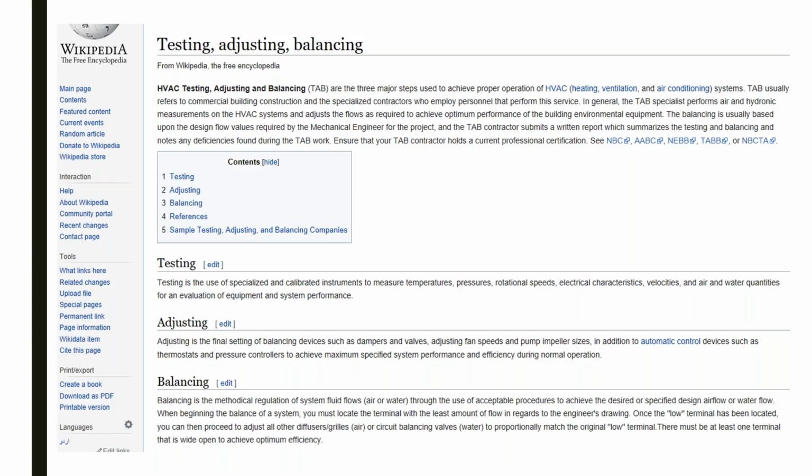I was a commissioning agent on a building where I was to verify tab by a random sample, and so I got the tab supervisor out. I know him very well. I don't know the guys that actually did the work. So a random sample, there's only like 16 VAV boxes in the entire building. We pick one, he reads it, nothing's right. Nothing matches the report that I'm looking at. The values are way off. Okay, that's one down. So we keep going.